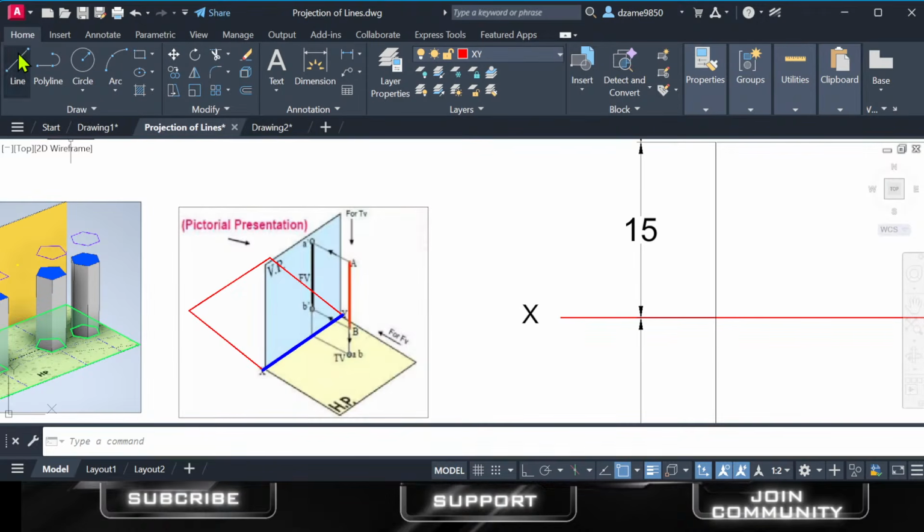Like you can see this point. From this point, I want to demonstrate this one. That point is parallel to that one, but parallel to that one again, down something like this. And you can say this is perpendicular. It is meeting at 90 degrees if you measure this one. And if it was directly in front of you, it becomes like this angle. Pay attention to that. The line is perpendicular to the HP. Its front view shows the true length.